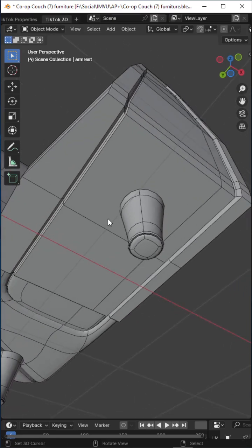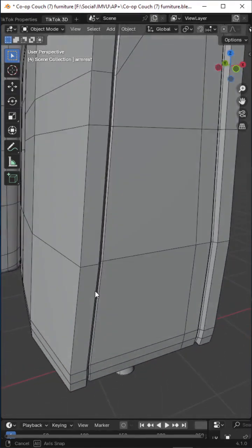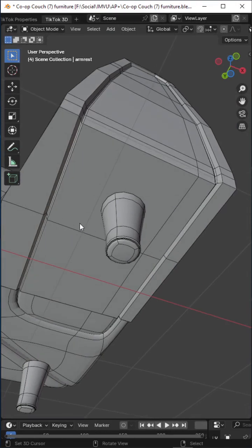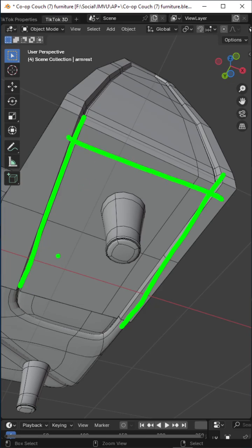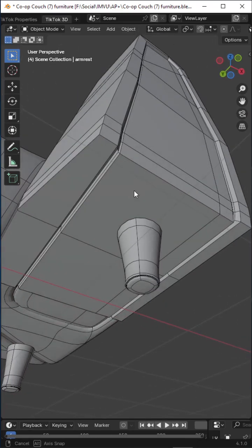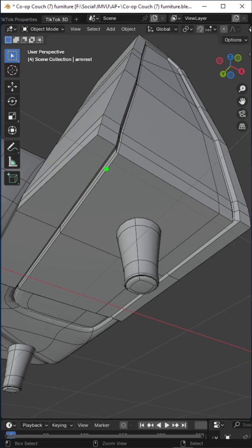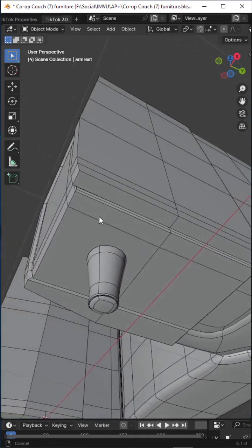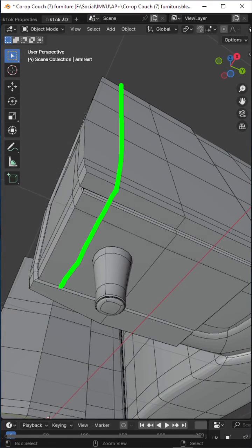Because there's a problem depending on how you structure your meshes. When you assign the subdivision surface modifier, we want this section to extend beyond this corner, because the structure of the mesh itself causes problems when you add a subdivision surface modifier, especially when you have a restricted shape as the basis for which you have the subdivision assigned.